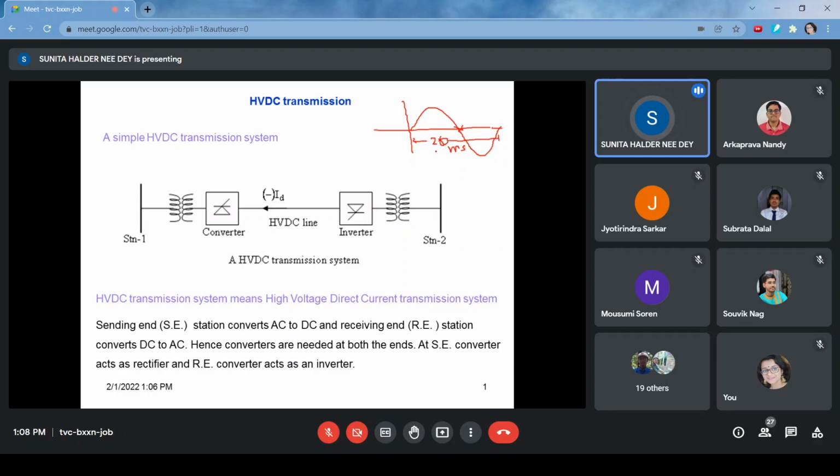So if we assume that a fault has occurred near the peak or anywhere within 10 millisecond, we shall get one zero crossing, right? During a fault, the current is very high, so we have to disconnect the circuit. If we want to disconnect the circuit at a very high current, there will be arcing, there will be energy loss. Now, if we can disconnect the circuit near zero crossing, then that problem will be less. So that facility is available in case of AC currents. That is totally absent in case of DC current.